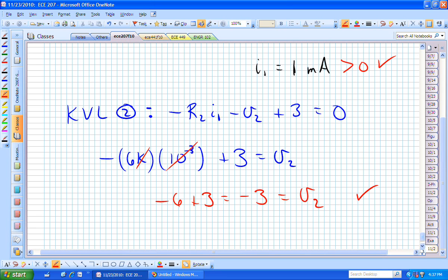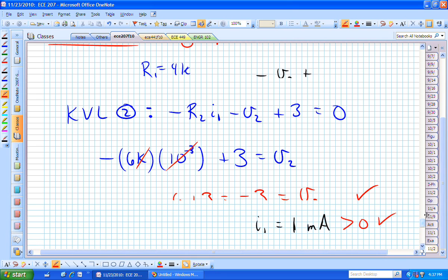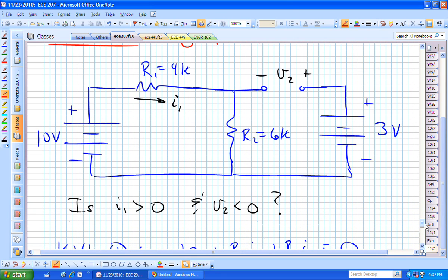Question? I thought we wanted the voltage across it to be 0. No, we want the voltage across that non-conducting diode or reverse bias diode to be negative. If it's going to be not conducting, we need that particular voltage to be negative across diode 2. Across diode 1, it's an ideal diode. We have 0 voltage drop, but the current is flowing. Positive current is flowing through that diode based on the arrow of that triangle in diode 1.